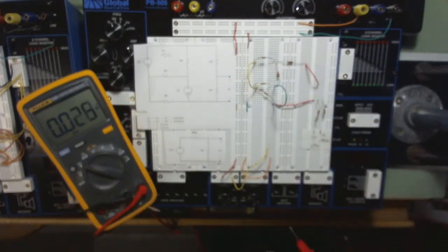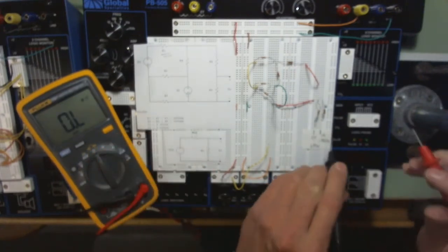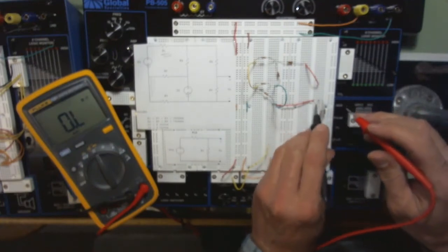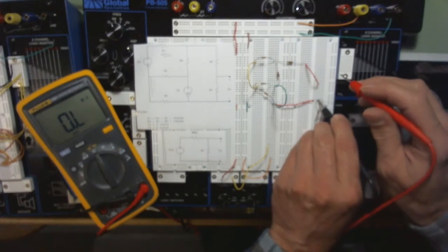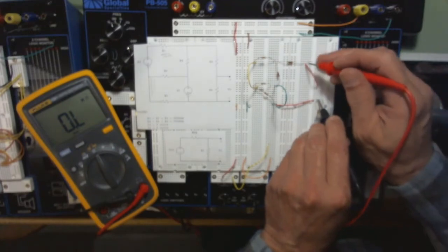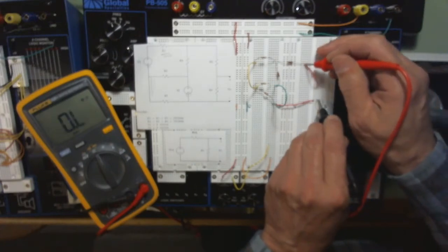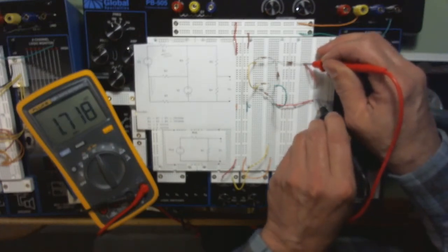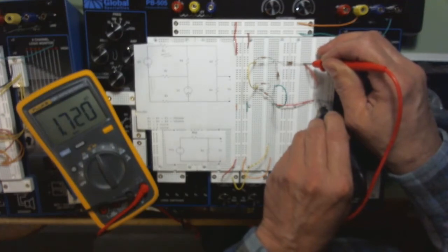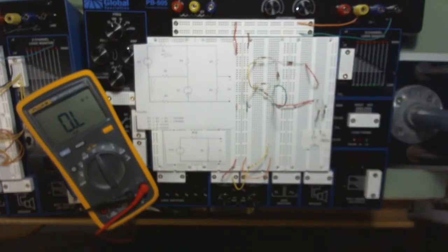And then I just look back into these terminals on this thing, set the resistance, and those that have done the calculation, hopefully everyone's done the calculation, they have some idea what this should read. Now, I'm not going to put my probe right there just because it's a little bit harder to get that. It'll be the same value right there, assuming there's no resistance in this wire. So I'll measure that, and I get 1.72 k ohms.